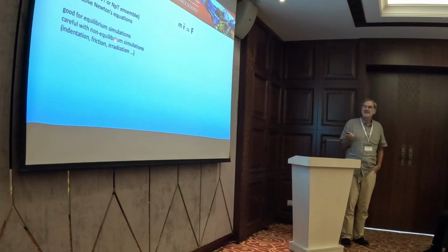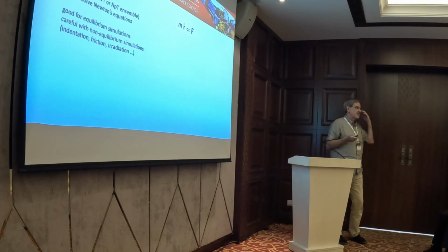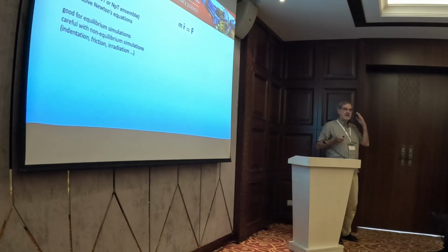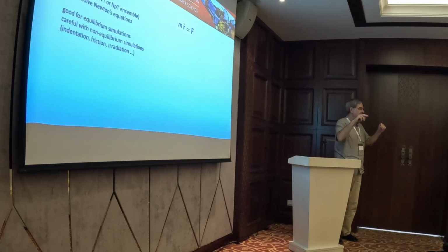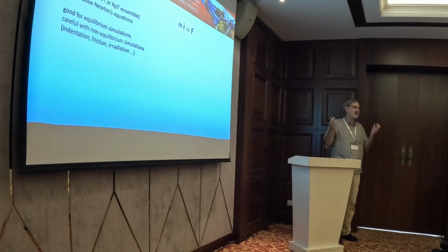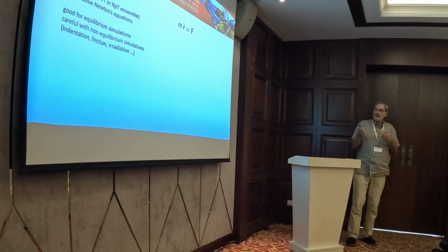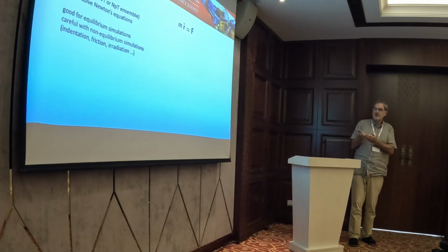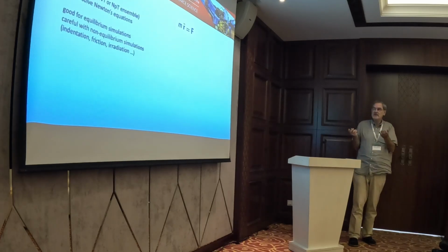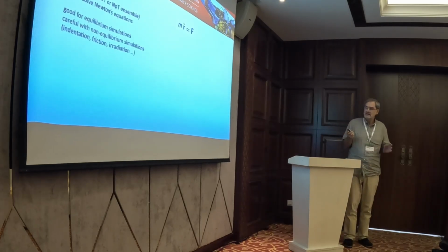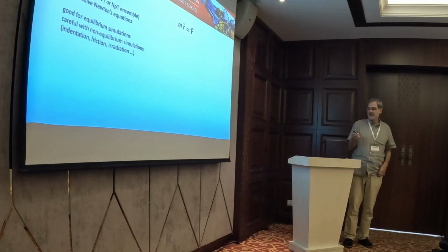I often get papers to read or to review that do non-equilibrium simulations with a thermostat. And then you think, what does this mean? I mean, this is a non-equilibrium simulation, a non-equilibrium condition, but there is a thermostat. So there is a daemon inside that fixes the kinetic energy. This is not realistic any longer. You cannot believe such simulations. So this is just a warning. If you use a thermostat, make sure it's for a thermal equilibrium simulation, because then it can be justified. But if it's not in thermal equilibrium, it may give rise to artifacts.